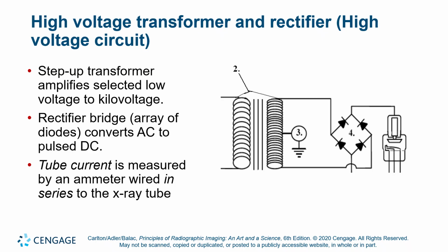And now reverse the magnetic field. That is, flip your hand over and then flip it back and then flip it over and then flip it back. And notice that that point in between your knuckles is halfway between the north and south poles of the flipping magnetic field. And then when you flip it over, it's still halfway between the north and the south poles. So there is no changing magnetic field at the very middle coil of a transformer. So theoretically, there is no high voltage there.